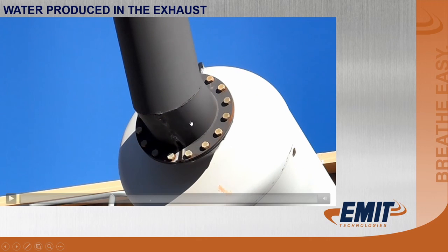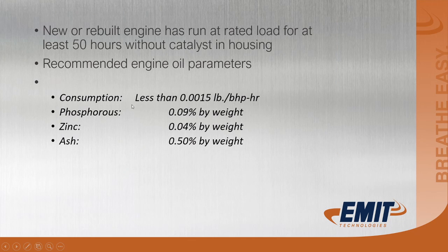Okay, and it's just amazing how much water is produced, but it's dried off right away. Don't leave those catalysts wet for long periods of time. Don't leave them in the back of a pickup or sitting outside on the ground. It will damage the catalyst.